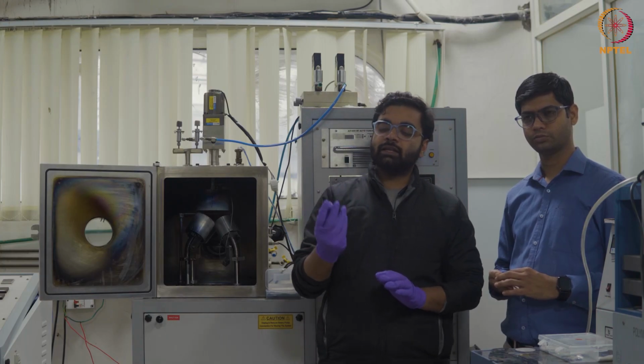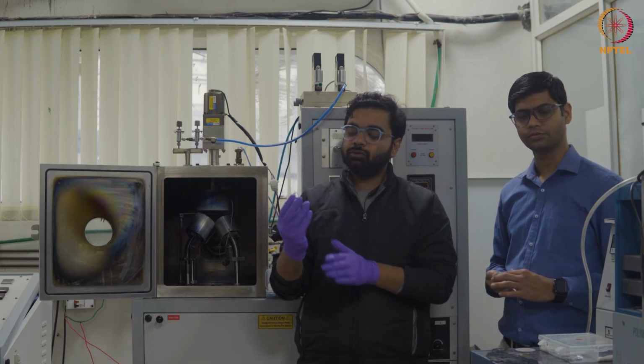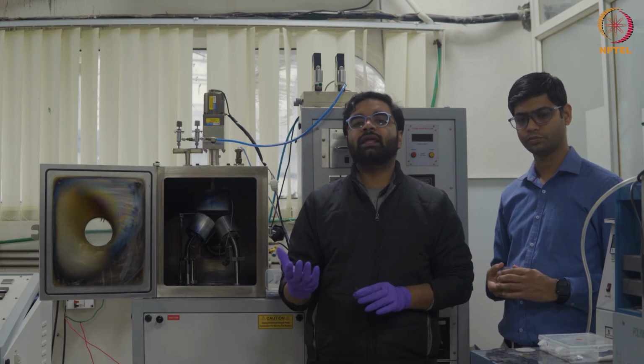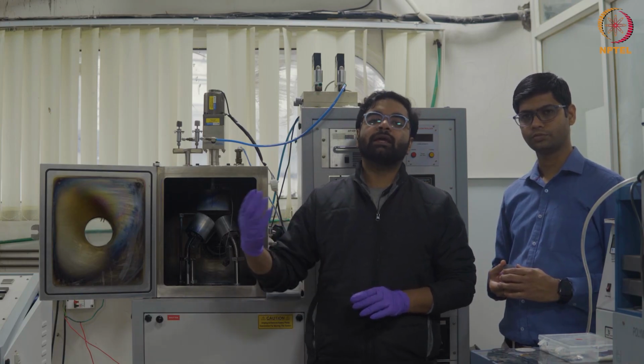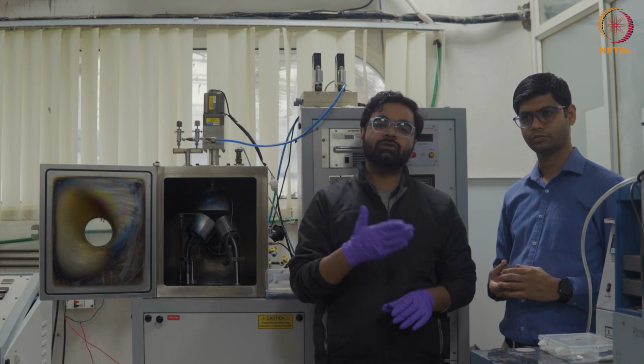The next step, once the material is spin coated with a sacrificial layer, is to give heat to it. It is about 80 to 100 degrees of heating, done by keeping it on a hot plate. It can be done in an oven as well, so it is not really binding that you use a heater only.